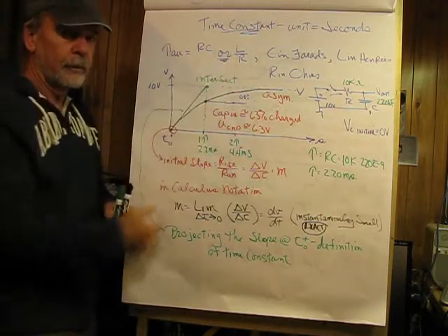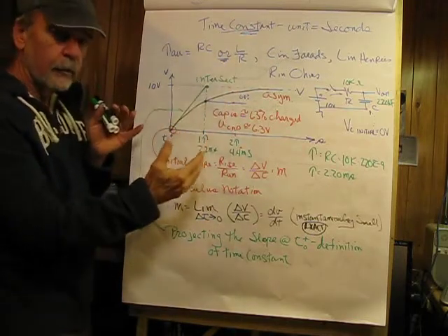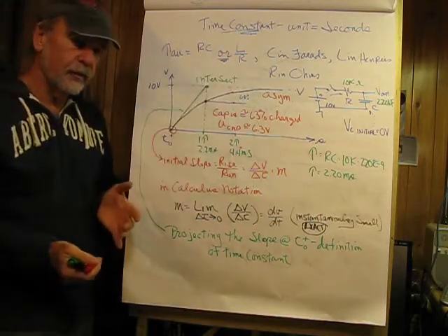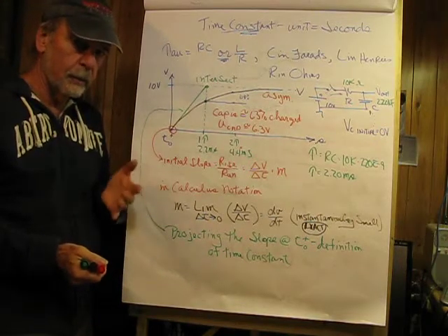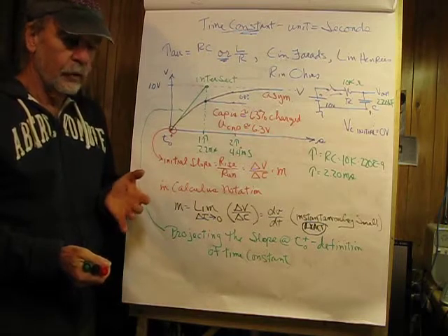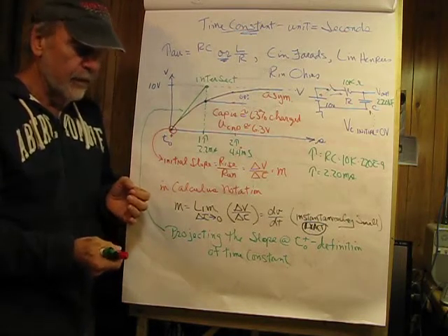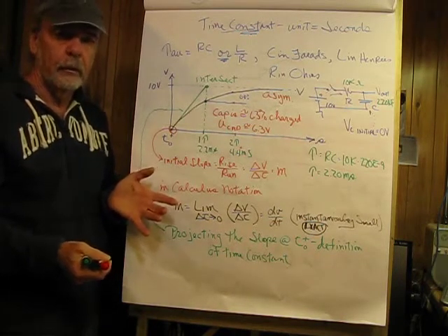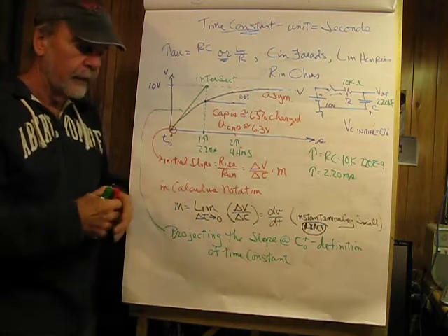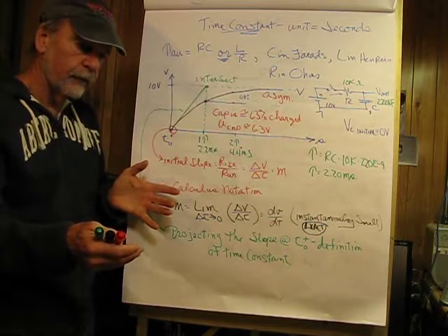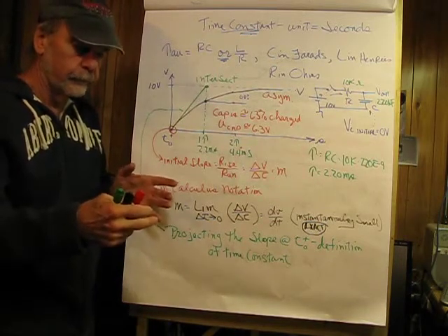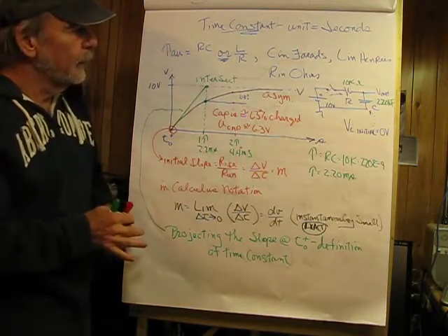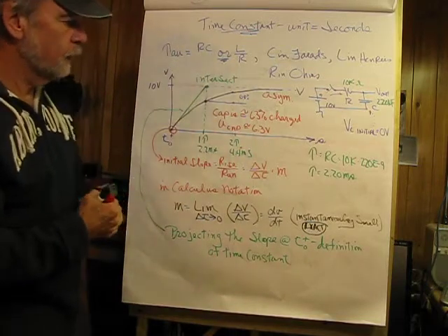So the smaller R becomes, the longer it takes the magnetic field around L to collapse. Now, we're not going to address this because inductors used in circuits aren't really too desirable unless you're in a switch mode power supply. The reason is they're costly. They have to be wound. They take up more board space, and they're subject to interference because they're a coil of wire, otherwise known as an antenna. They radiate energy. It can be near field or far field: near field is flux returning, and that which does not return is a radio wave. Anyway, we're going to be focusing on RC time constants.